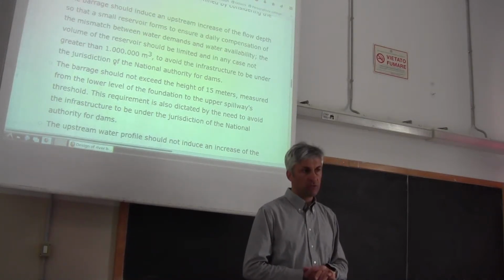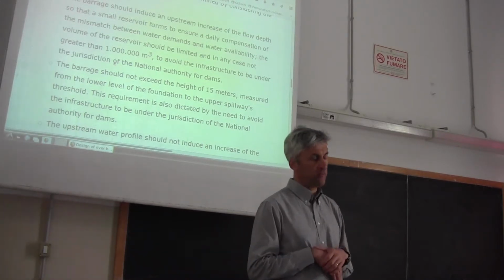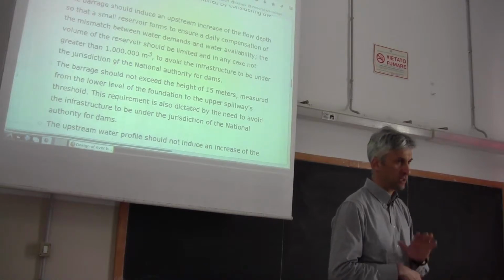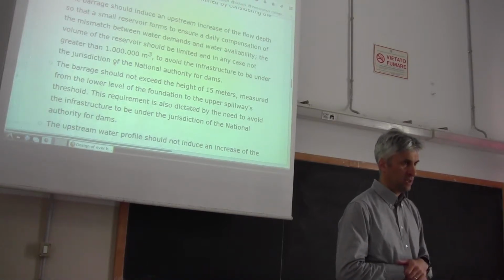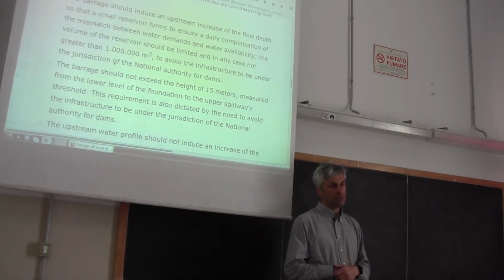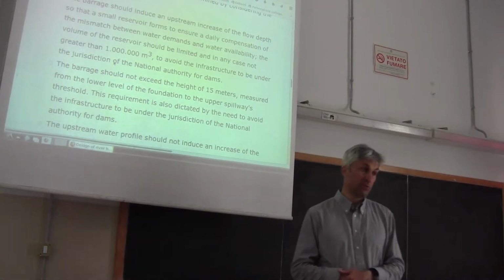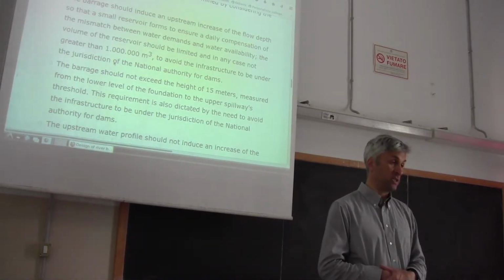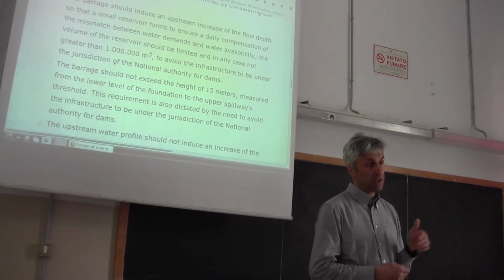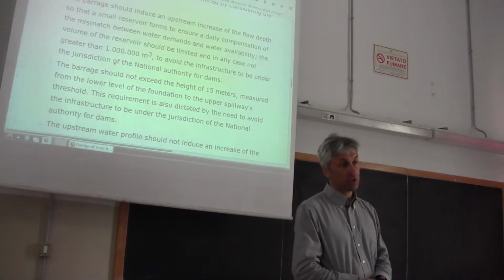And once you know the volume that you need, of course, you place the elevation of the environmental flow spillway. Is it clear so far? Okay, now we have to determine what is the elevation difference between the environmental flow spillway and the next spillway in terms of priority. The next spillway is the diversion spillway.